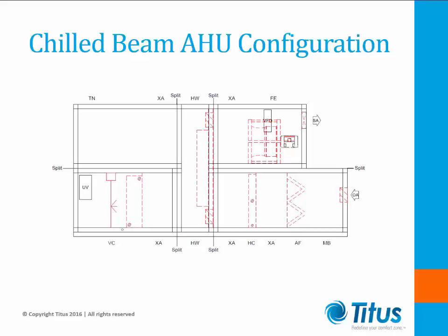Chilled beam systems provide energy savings through reductions in transport energy. It is more efficient to transport BTU per hour with water than air. To do this, these systems use the least possible airflow to maintain space conditions.